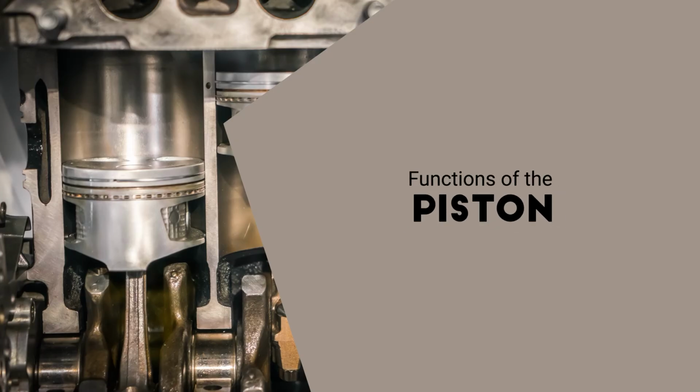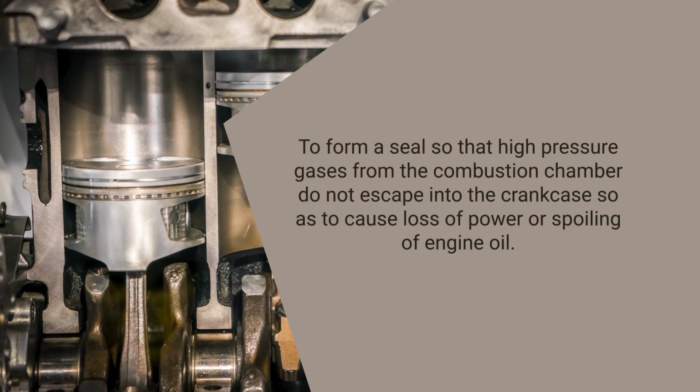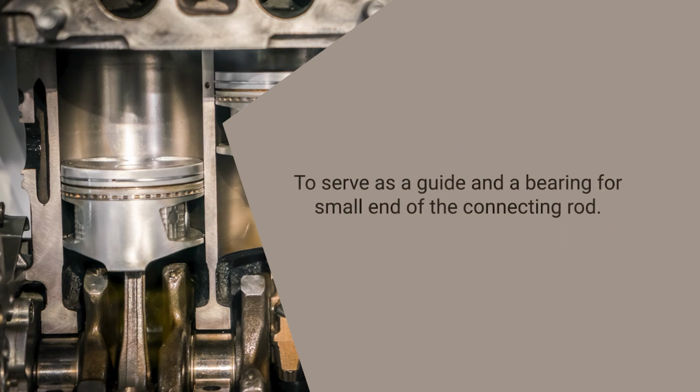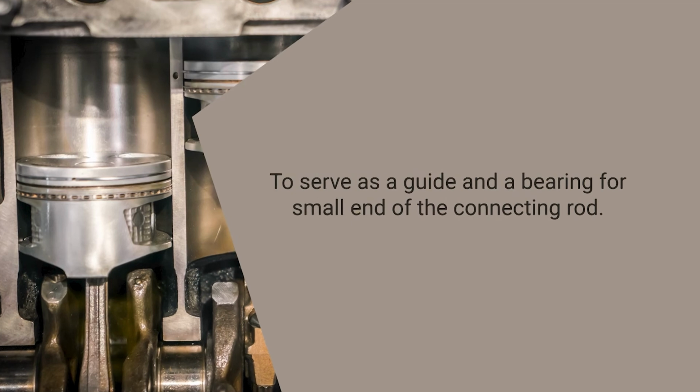Now, what is the function of the piston? Please remember that the piston is a very important part in the motorcycle, because it transmits the force of explosion to the crankshaft. It forms a seal so that high pressure gases from the combustion chamber do not escape into the crankcase, so there is no loss of power or spoiling of the engine oil. It also serves as a guide and a bearing for the small end of the connecting rod. It basically guides the direction of the motion.